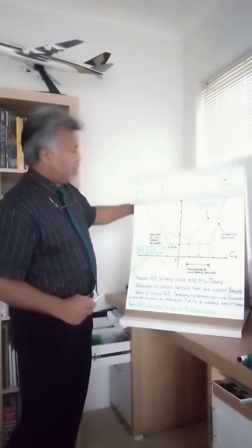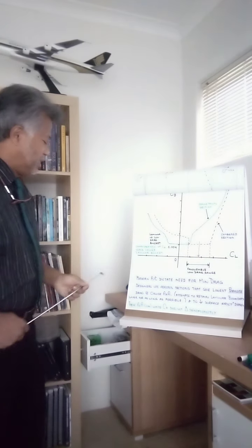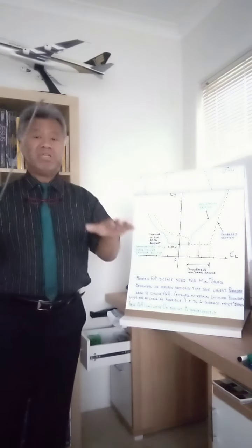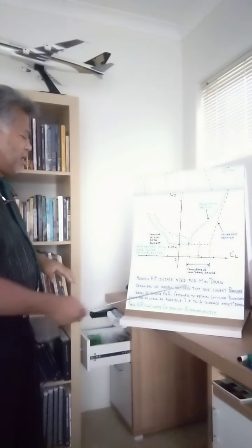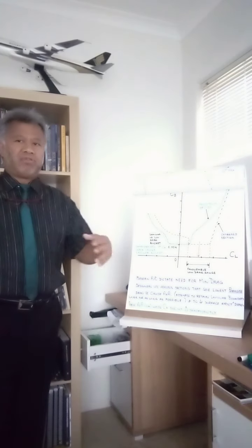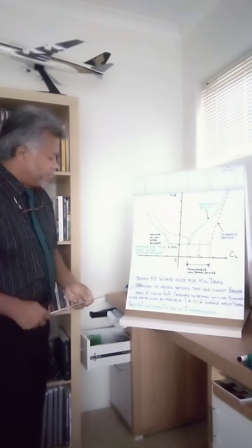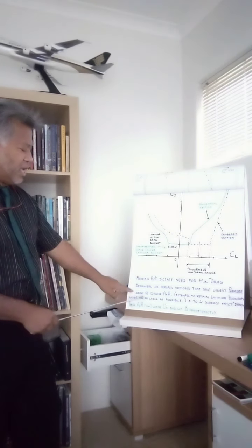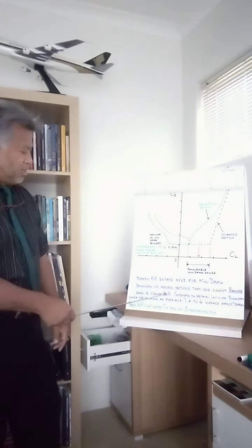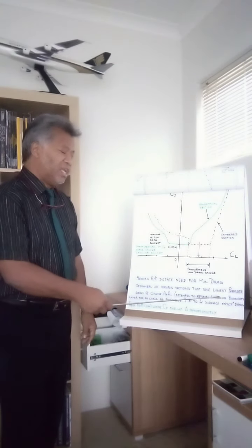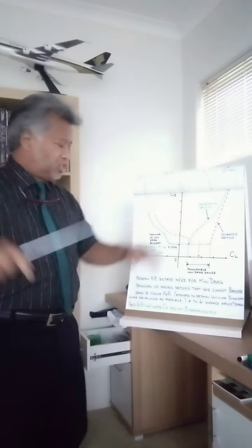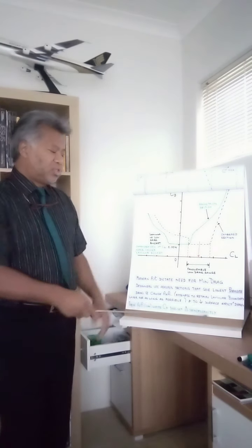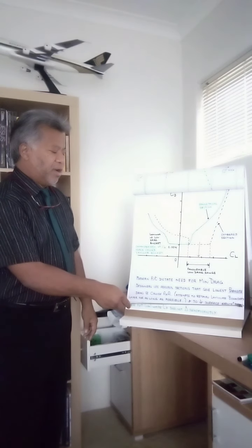That graph gives you an idea of how all these things work together. One final point I'd like to touch on is that modern aircraft dictate a need for minimum drag. They want to fly with minimum drag for savings in fuel costs and so forth. So designers usually use an aerofoil section that gives the lowest parasite drag at the cruise angle of attack, which means it attempts to maintain a laminar boundary layer consistent with the flow for as long as possible, and to reduce the surface friction drag.